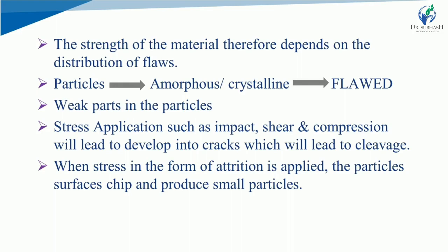Now, when you apply stress on them, like impact, shear, compression, this will lead to developing cracks in them, which will lead to cleavage, that is nothing but the breakdown. When the bigger particles cleave or break down, then they will be distributed or broken down into small particles. This is the ultimate size reduction mode.